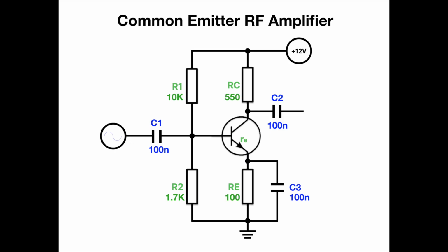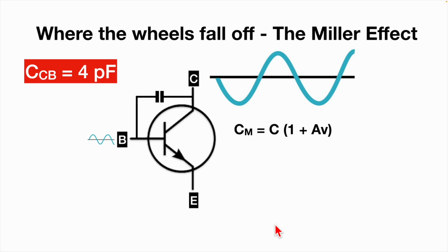So that means my much larger collector resistor is being divided by this tiny amount. So actually the voltage gain of my amplifier is something like 220. It's minus AV because it's inverted, because we're taking it at the collector. 220.